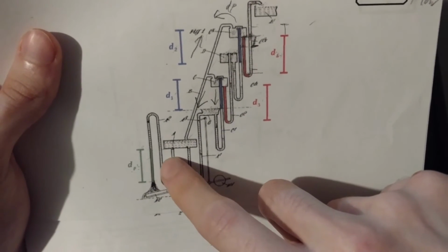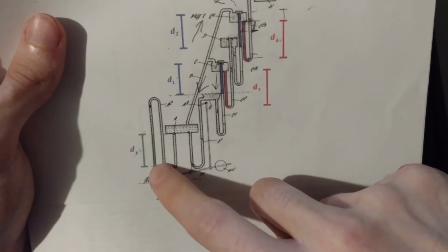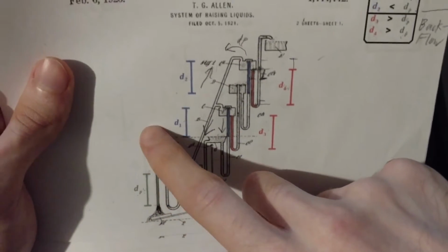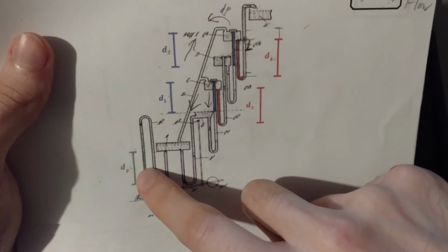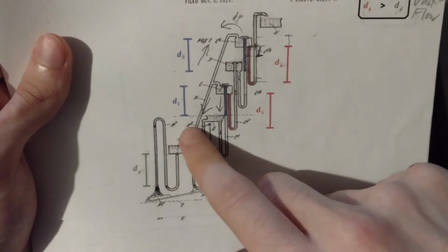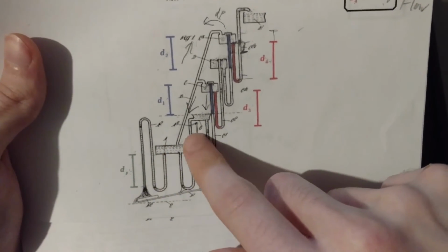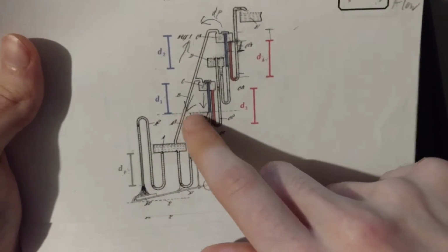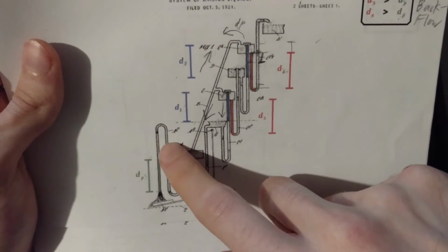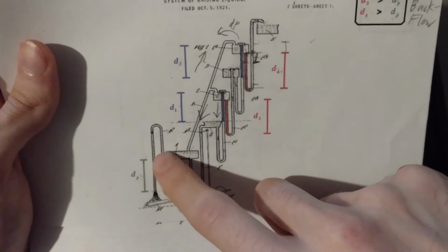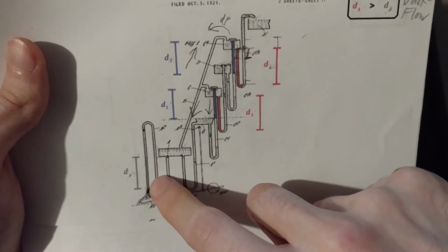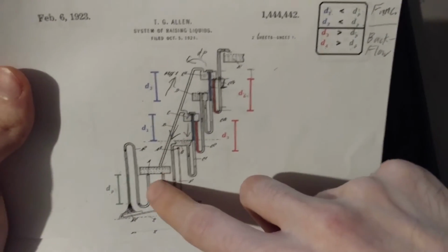32, 33 feet or 10 meters or whatever, what will happen is the suction will become so great inside this tube here that the air is actually going to separate out from the water if this water hasn't been degassed, which you're going to be using this outdoors, so unless you run a degasser first before putting it into your feed tank, there's going to be a whole bunch of air that's going to show up in this tube, and it's going to kill your siphon. So you do have a limit for your suction cycle, but pressure cycle you don't.